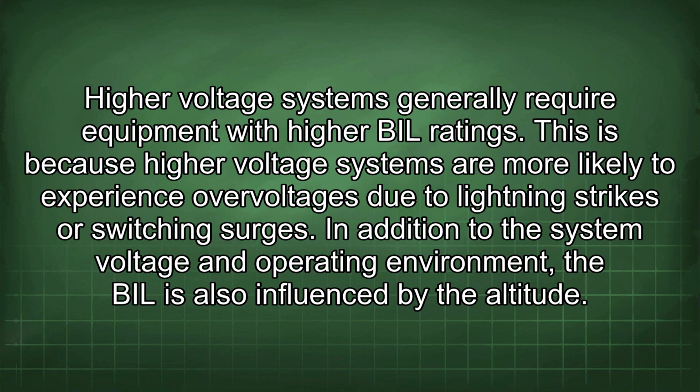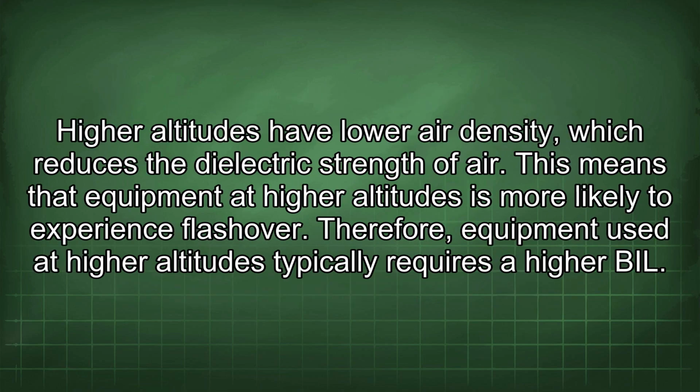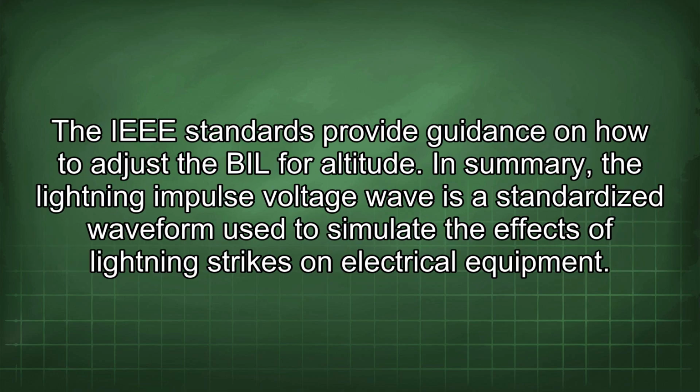In addition to the system voltage and operating environment, the BIL is also influenced by the altitude. Higher altitudes have lower air density, which reduces the dielectric strength of air. This means that the equipment at higher altitudes is more likely to experience flashover. Therefore, equipment used at higher altitudes typically requires a higher BIL. The IEEE standards provide guidance on how to adjust the BIL for altitude.